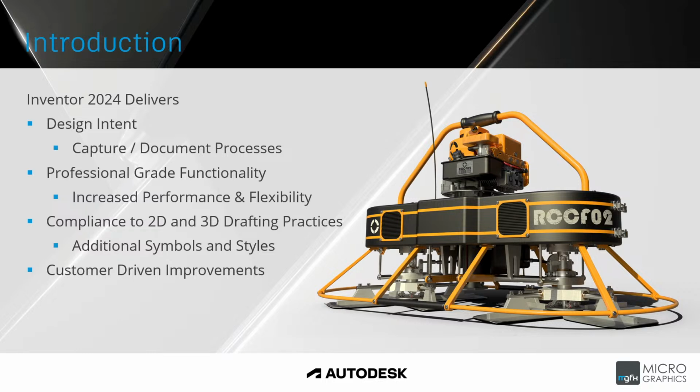The next section of areas of improvement is to bring professional grade functionality to Inventor with improvements in performance with faster hole and punch feature patterning. Also the ability to create custom or cut back elbows, so you're no longer limited to 45 or 90 degree elbows within the tube and pipe environment. It's also support for user-defined IBLs or image-based lighting environments for the creation of realistic renders.